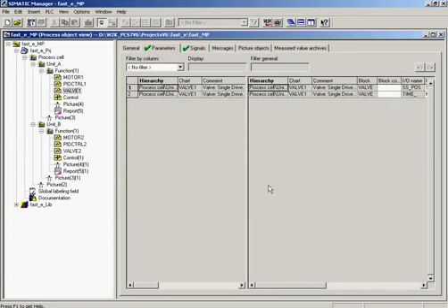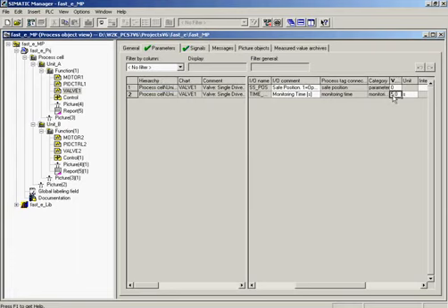For clarity, we will split the window again to display the chart column in the left section and the measuring point connection, category, and value columns in the right section. Now we can enter the value 6. To change the monitoring time of valve 2, we select the input field in the left section of the process object view valve 2 and enter the value.